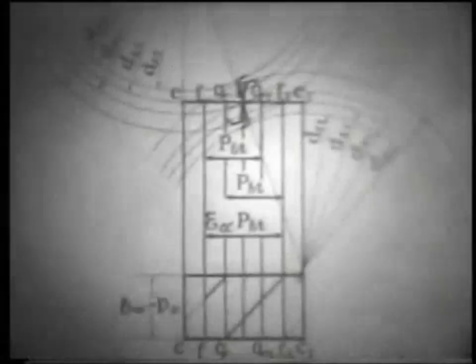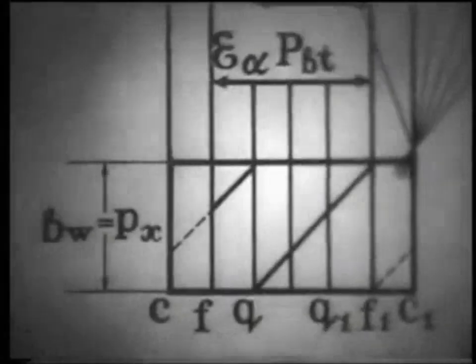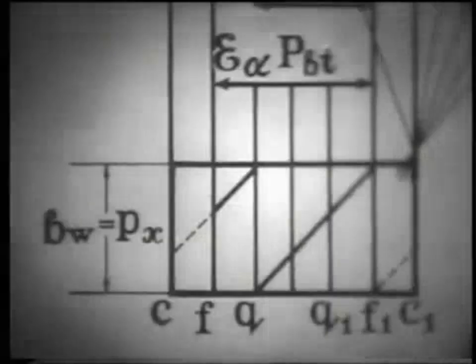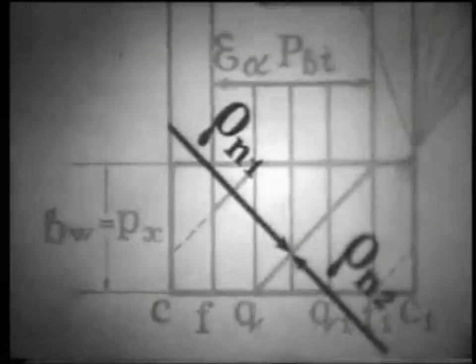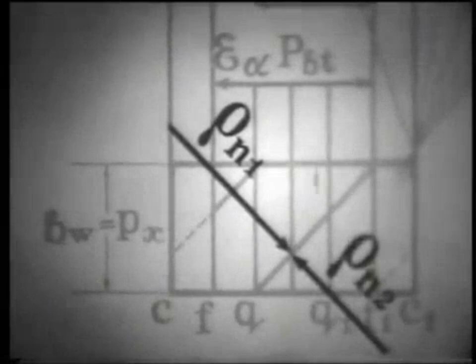Let's consider the features of the skew gear operation. Its advantage is that there are always several pairs of teeth in the engagement. The total length of the contact lines is much longer than in a straight tooth transmission. The radii of curvature of the teeth are also larger. This determines the increased load capacity, lower dynamic load, smooth operation and noise reduction.